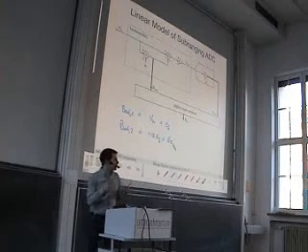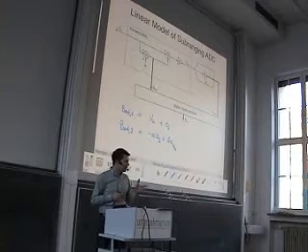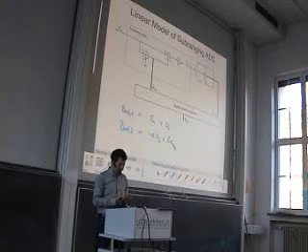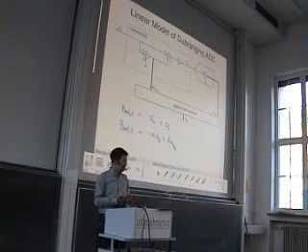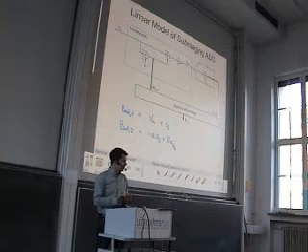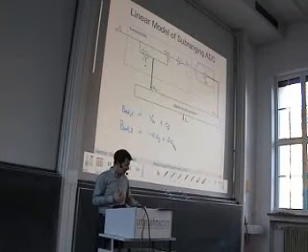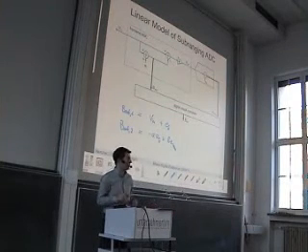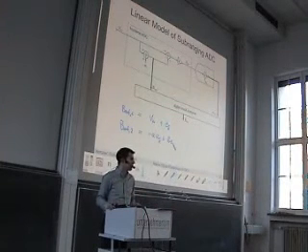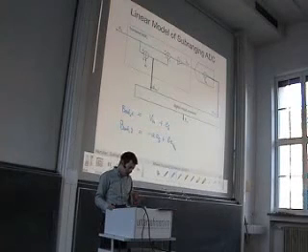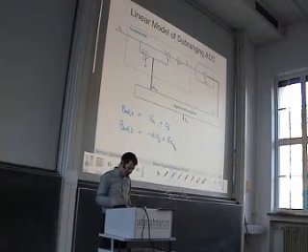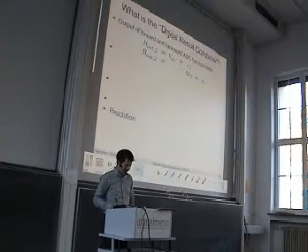Okay, now you have two outputs, one of the front end ADC, one of the back end ADC. The question is, how can we combine them? You can see both outputs contain a quantization error. And to get a precise result, it is desirable to have a very small, or in the perfect case, no quantization error. So if we look at these two equations, we can think about how to get rid of the quantization error.